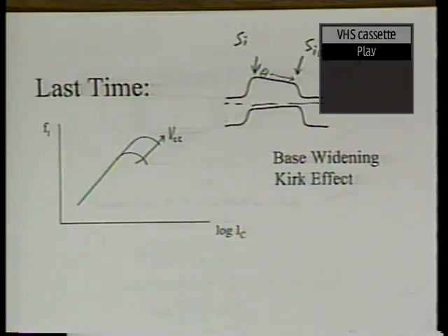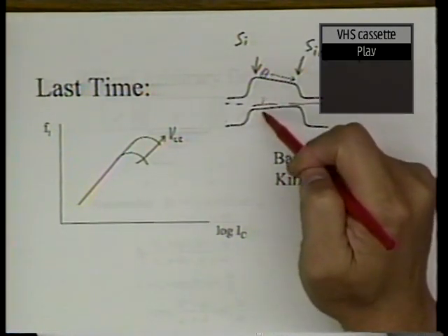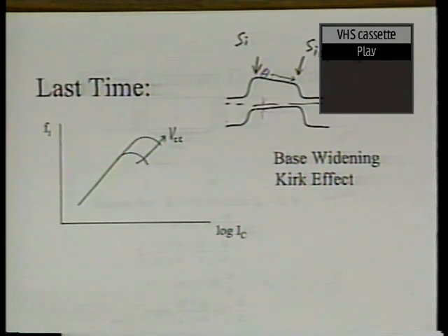Turi, yeah. I don't know, the question maybe is related to... Sure. Reach over, get a microphone, please. Thank you. So, but it seems like how the Fermi levels are set will determine which one... That's right. Is that the question? Doping, that's exactly right. You see, there's a relationship that doping concentration determines the spacing between the Fermi level and the EV. This is p-type material.